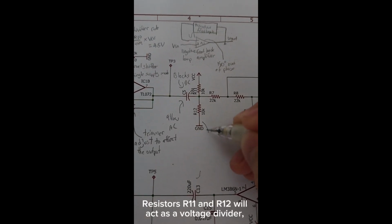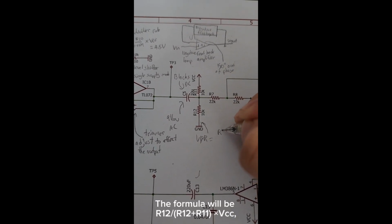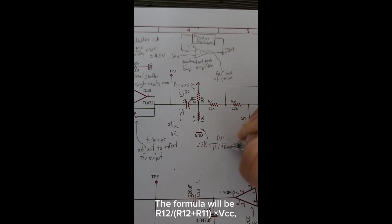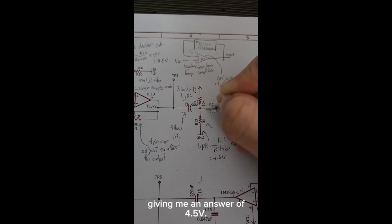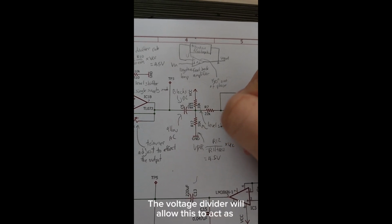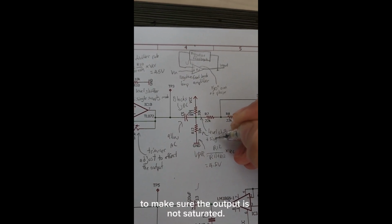Resistors R11 and R12 will act as a voltage divider at 10k ohms each. The formula will be R12 over R12 plus R11 multiplied with VCC. VCC will be supplied 9 volts, giving me an answer of 4.5 volts. The voltage divider will allow this to act as a single supply mode and a level shifter to make sure the output is not saturated.